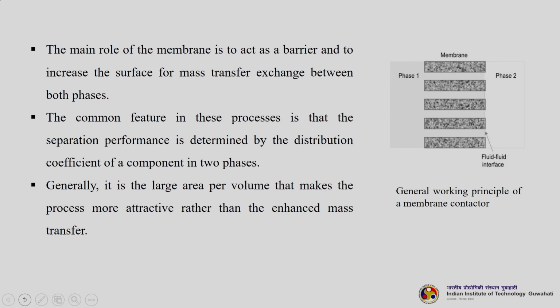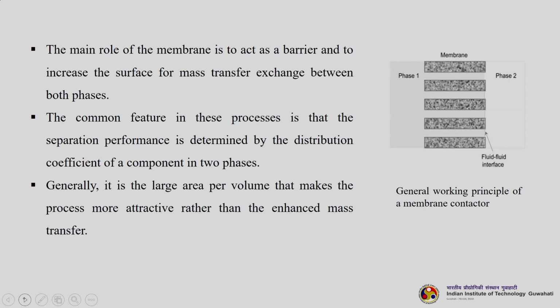The common feature in these processes is that the separation performance is determined by the distribution coefficient of a component in the two phases. Which solute you want to separate, and what its distribution coefficient is in both phases, plays a big role in deciding how the solute will be transported, apart from other governing factors. Generally, it is the large area per volume that makes the process more attractive rather than enhanced mass transfer.